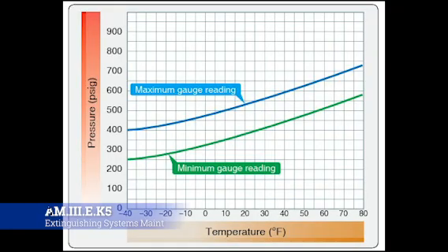Now that we understand the fire suppression systems, what sort of maintenance can we expect to have to do on them, and what kind of concerns do we have about working on them? Okay, so the most common maintenance task associated with fire bottles is simply inspecting the pressure. You'll do this every so often. You'll go up there and just look at the pressure gauge that's on the outside and make sure that the needle is in the green arc. That's really all there is to it.